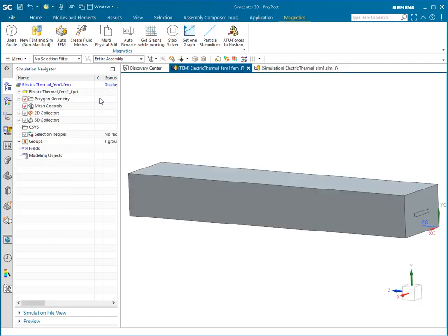So in the fem file, check that we have already some basic information here. We have already a basic air material. So for later creating meshes with air, we simply will put them into this collector, and this collector already has the properties that we need. The fluid, physical, and the material property for air is already there.